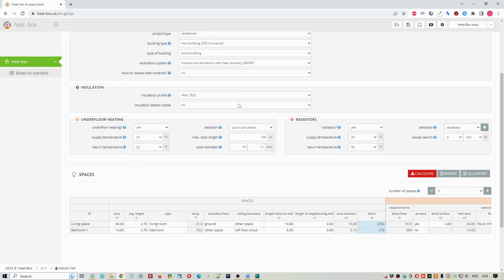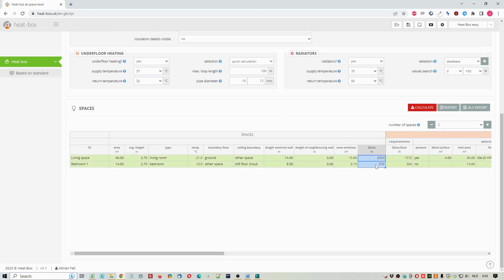This is quite strict, because the average temperature in buildings is closer to 18 degrees. As a result, the heat loads we calculate are a little bit over-dimensioned, and compared to a detailed calculation, according to the BS EN 12831 standard, we will end up with heat loads that are on average 5 to 10% higher. For the dimensioning of underfloor heating and radiators, however, this is not a problem, and this way we can be sure that the rooms will heat up adequately in all cases.